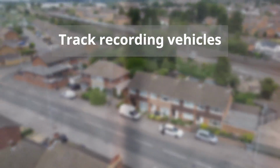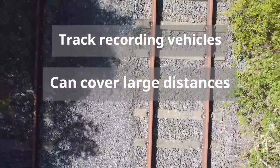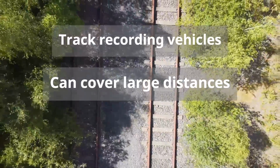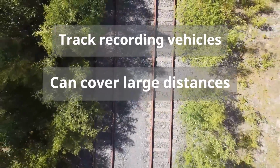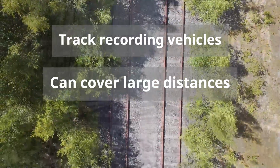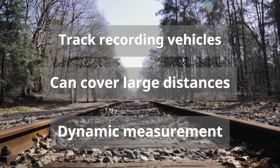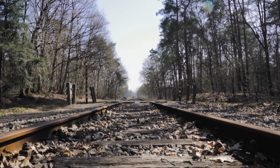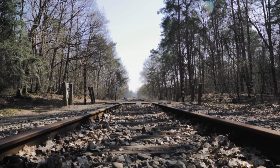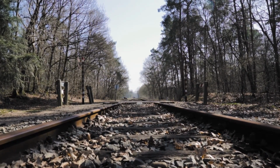They run all over the network, covering track at set frequencies depending on its usage, measuring track quality data. A key advantage of using train-borne recording is that the measurement shows how the track acts while under the load of a train, known as dynamic inspection, highlighting issues that may not be visible under static inspection. Some areas, particularly crossovers and terminal platforms, where it is not practical for the recording trains to be routed to record, have to be manually measured.